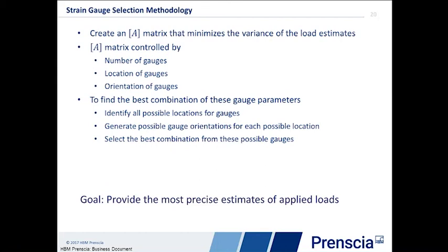That's the fundamental assumption here: that for each load case, I'll end up with a unique set of strain measurements off my gauges, and with those sets of unique strains, because of superposition, I can extract out what the loads are.